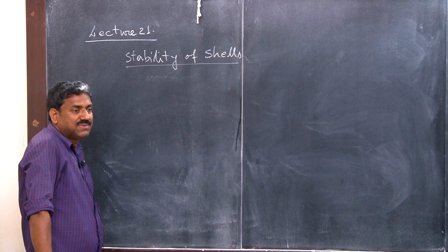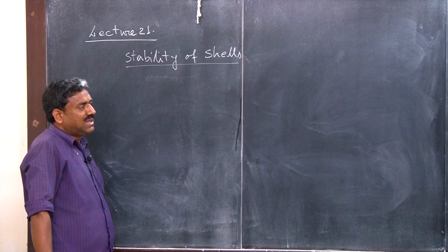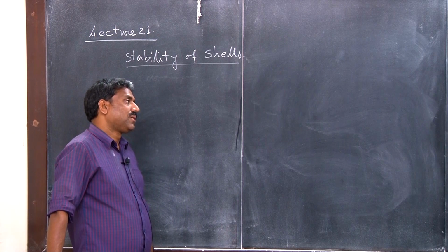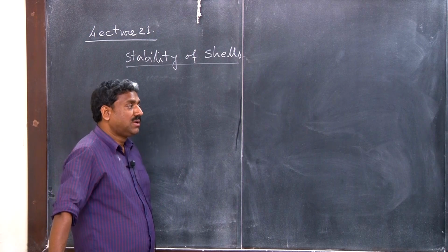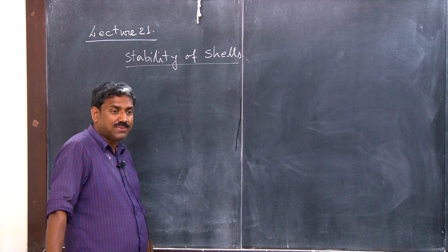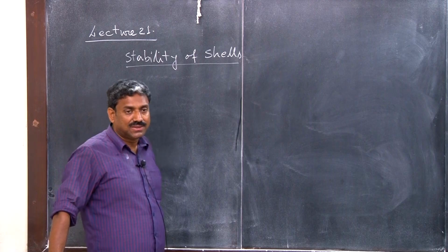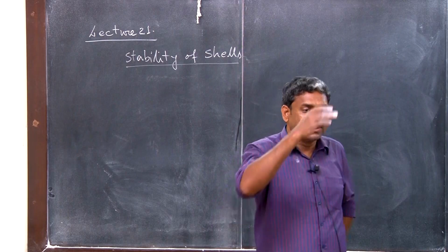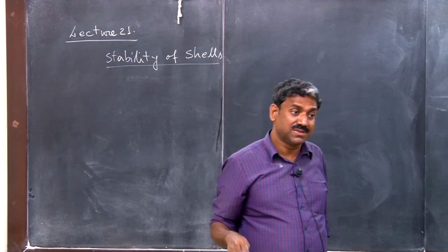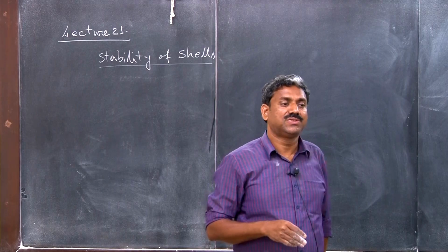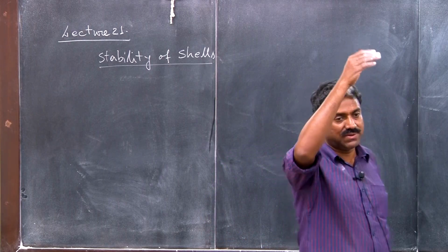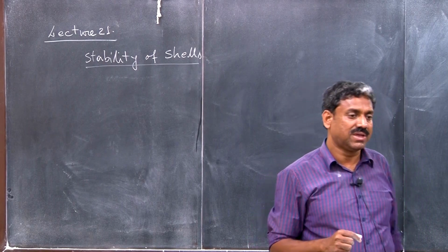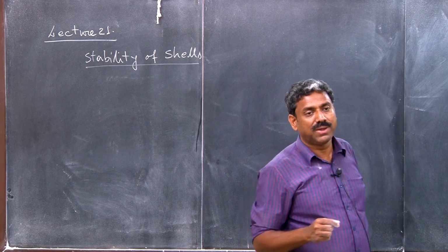That's why shell buckling is a very important thing, and we always take the example of shell buckling. Let us go back to our first discussion, where we showed you four kinds of systems. The third kind was a system showing stable and unstable asymmetric bifurcation behavior, where the ascending limb was stable and the descending limb was unstable, and it was extremely imperfection sensitive, notorious, because it follows 1/2 power law imperfection sensitivity.